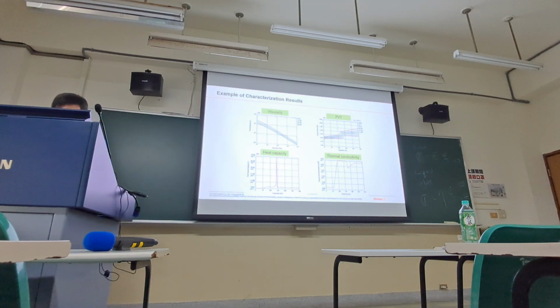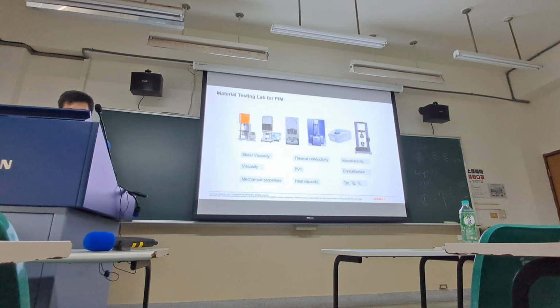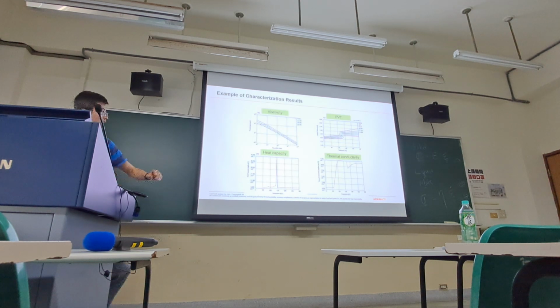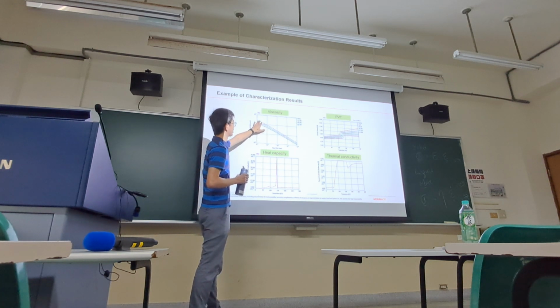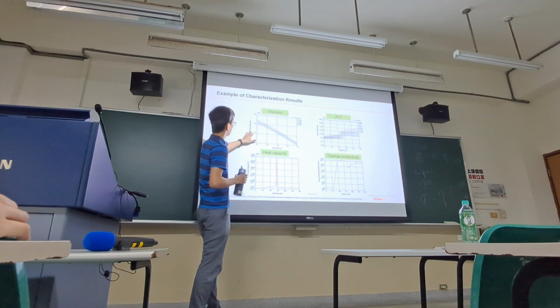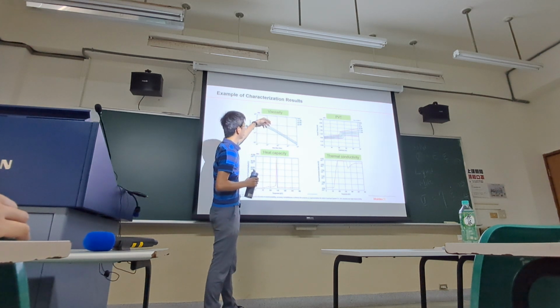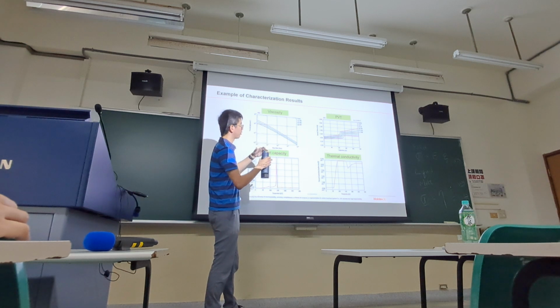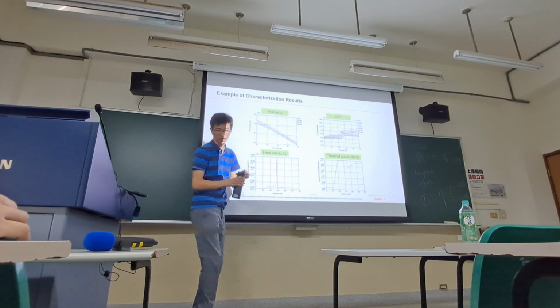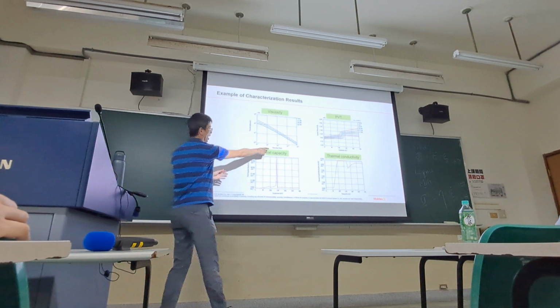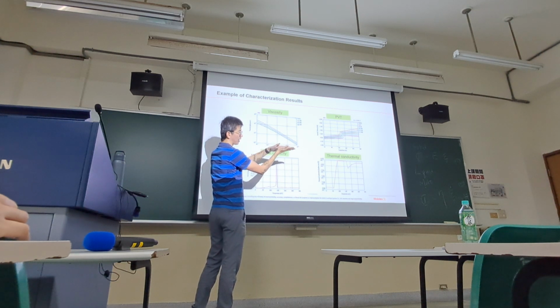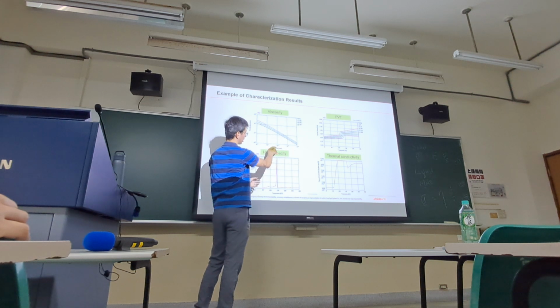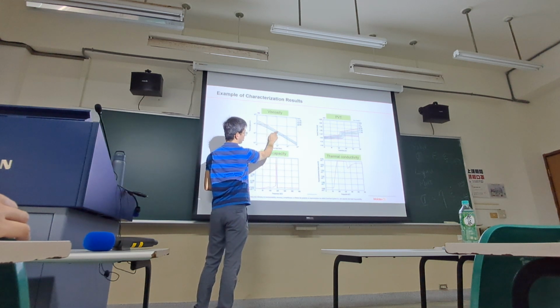Okay, so by those material testing methods, we are able to let you know what the viscosity is. If we increase the temperature, the viscosity, the resistance to flow, is reduced. And sometimes polymer is very interesting. If you apply a higher shear rate, the shear rate being the difference between the velocities, the flow resistance will drop.